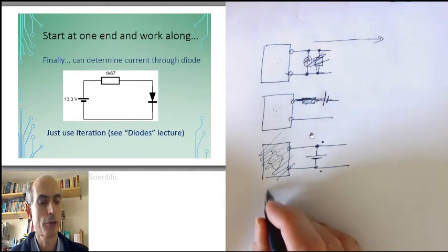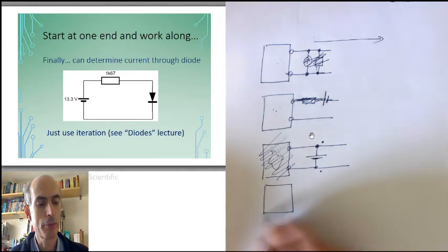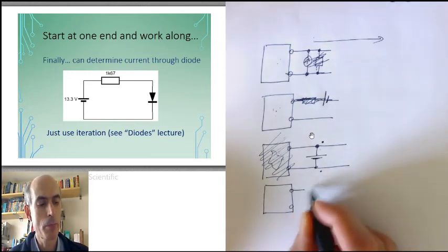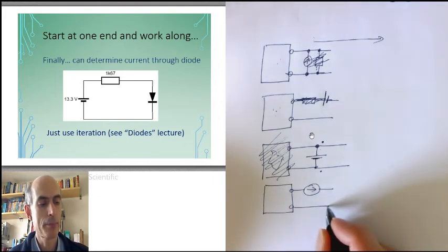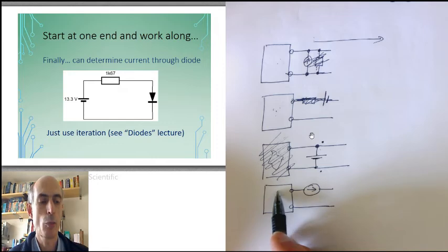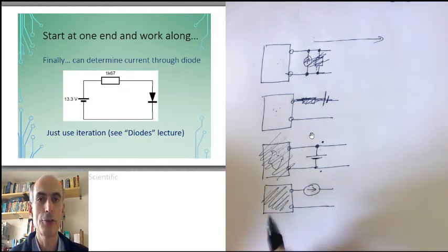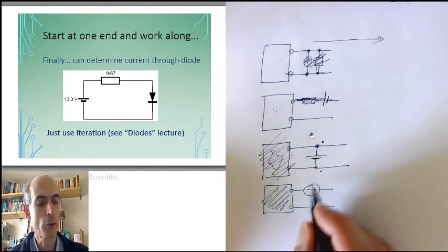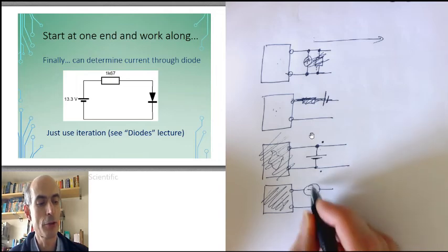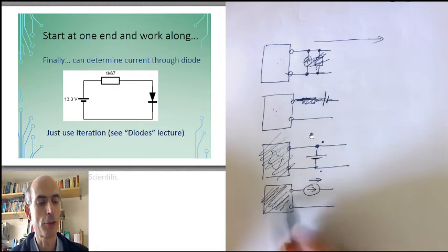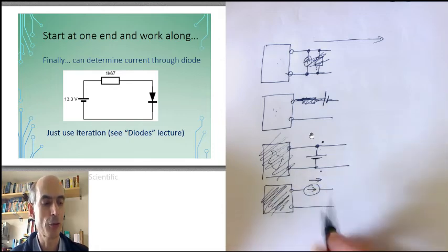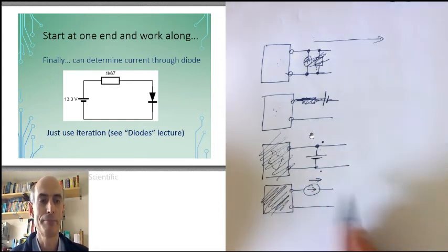Similarly, you might have started with a large number of components here and there being a current source. And once again, you've wasted your time analysing any of this circuitry in here. All you have to do is start from this current source and say, I know that the current from all of this stuff is just the value of this current source. I can carry on from here.